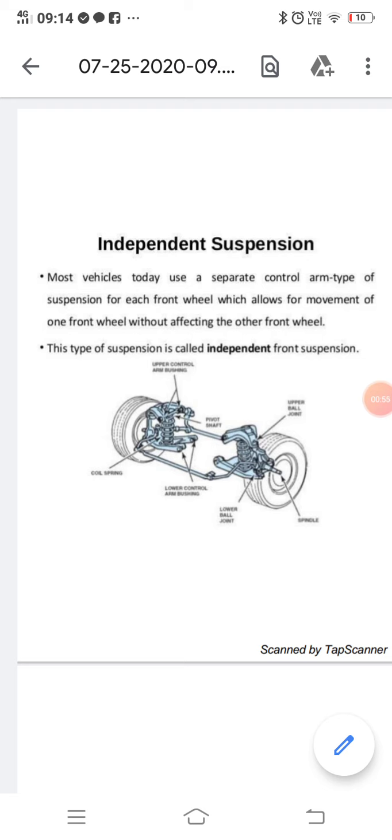Due to the absence of interplate friction, some manufacturers have used it for the rear suspension and some for the front suspension. Coil and torsion bar springs are superior to the leaf spring so far as energy storage is concerned. When we store energy, it is more efficient with a coil spring.